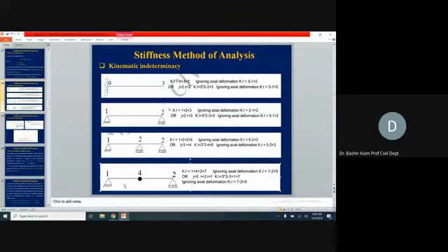One will be vertical, and because of this settlement and rotation, horizontally also it will be changing its location. So we have 1 vertical and 1 horizontal translation. So 2 translations and 2 rotations. That's why the total indeterminacy of an internal hinge is 4 degrees. Again, by simple addition of these individual joint displacements, when we sum them up, we get the total indeterminacy.